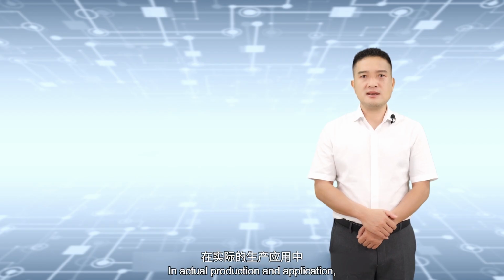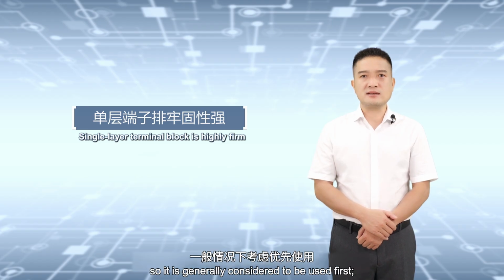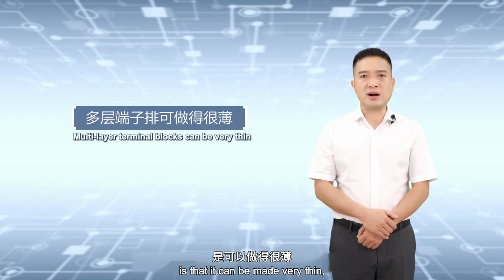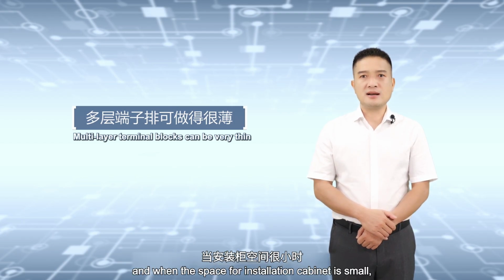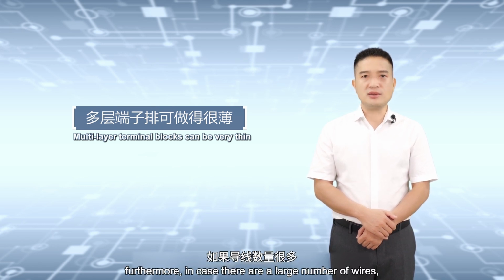In actual production and application, the single-layer terminal block has strong firmness, so it is generally considered to be used first, while the advantage of multi-layer terminal block is that it can be made very thin, and when the space for installation cabinet is small, it can save space. Furthermore, in case there are a large number of wires, it can be used first.